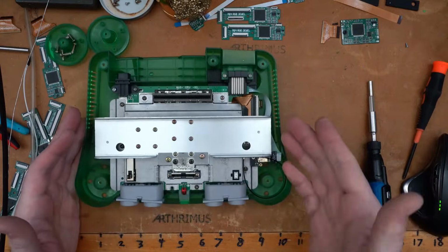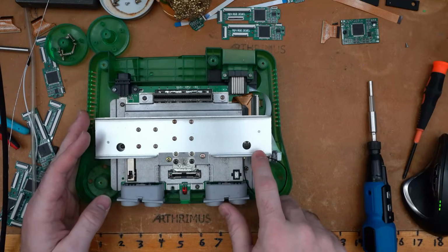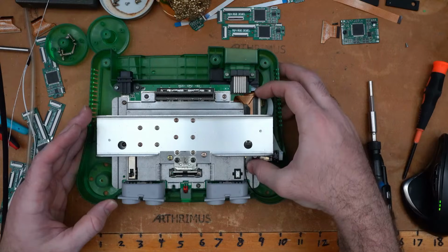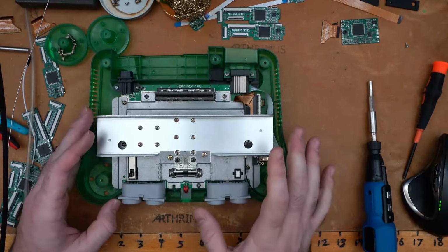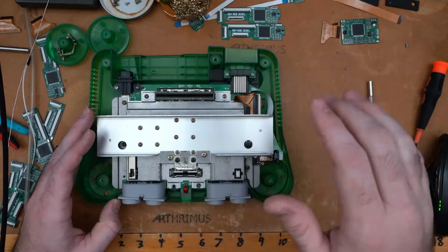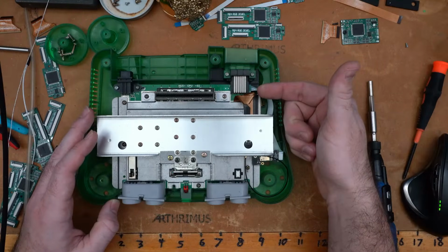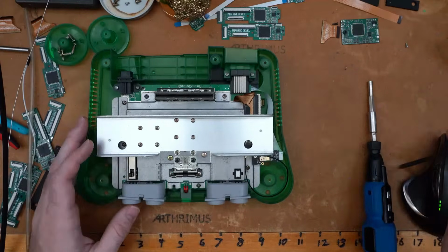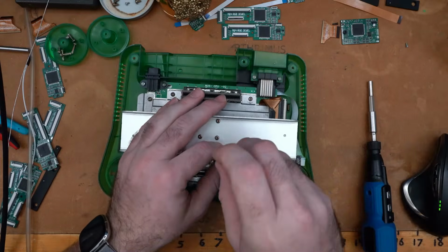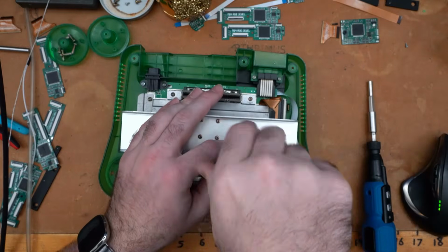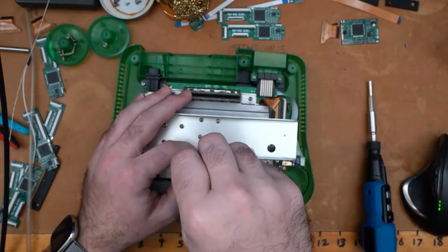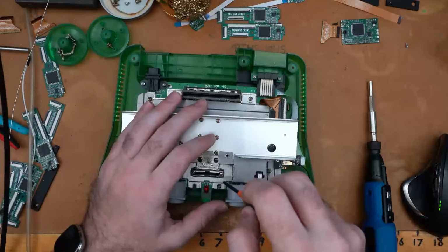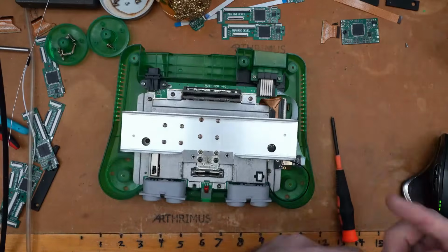So for the Retro GEM, you have to remove the top heatsink because the mounting screws for the Retro GEM are actually underneath the heatsink, and we need to have access to those. But we also need to completely remove the motherboard because we're going to be soldering to the AV out connector on the back side here. So we need to be able to flip the whole thing over. So we're just going to go ahead and remove the entire motherboard right now, and we'll go over how to put it back together once we get through here. So you basically just remove every screw, pretty much every screw you see.